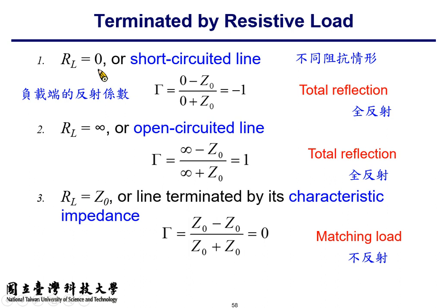If the reflection coefficient magnitude equals 1, then it suggests there is no loss on the load. The load didn't dissipate any power. All the energy is reflected if your reflection coefficient magnitude equals 1. Because both short circuit and open circuit do not absorb energy.